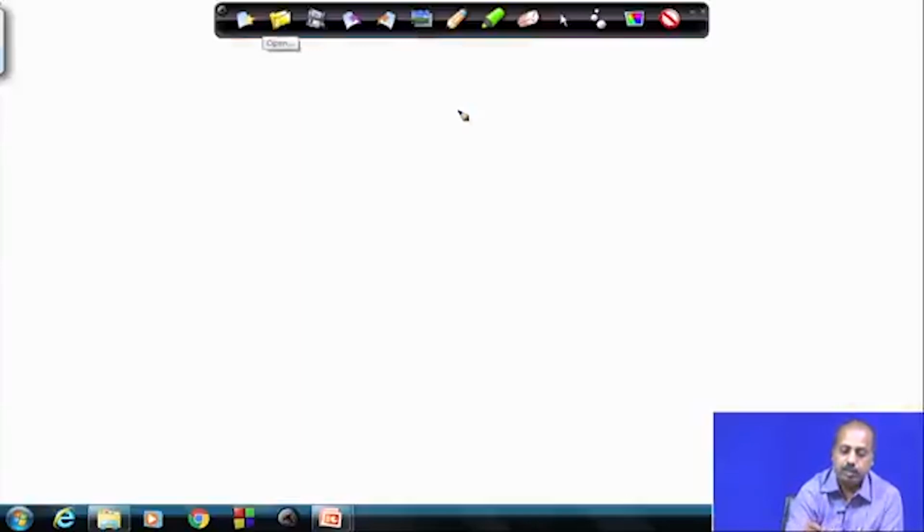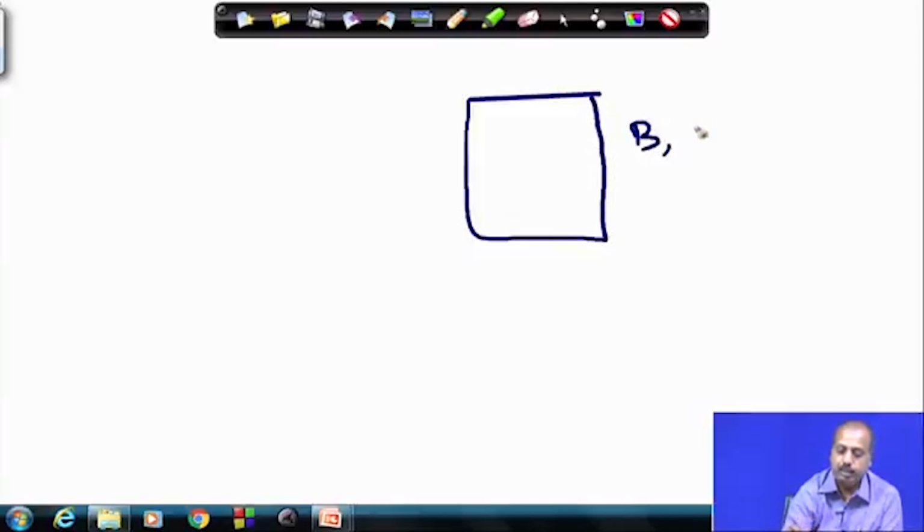Say like this. This is the subroutine, and this subroutine uses the registers B and C, and we expect that the contents of these registers should not be modified. In the body of this subroutine, it modifies this B and C. So, it works with these B and C registers, so that way they get modified, but we do not want these modifications to be reflected into the B and C values of the original calling program or the main program.